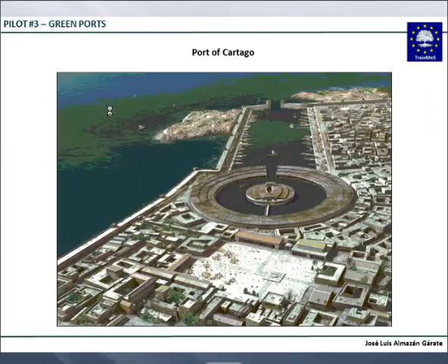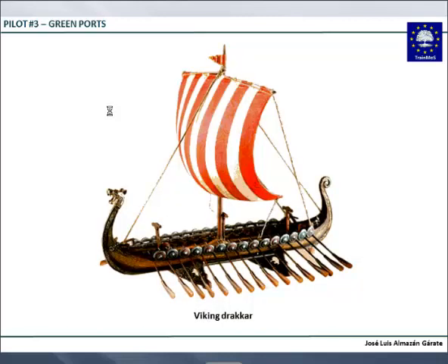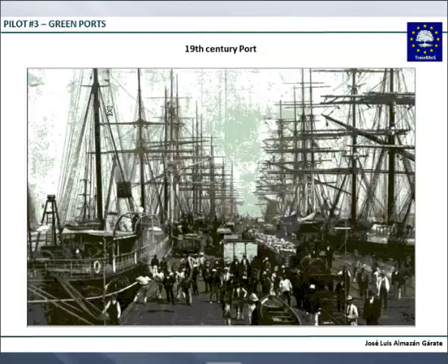So there are some places where ships have to get through, and those places determine the size of the ship. And it is the size of the ship that determines the size of the port. You do not make the port whatever size you want. It's determined by the places through which ships have to get through. And these are the ship lanes.